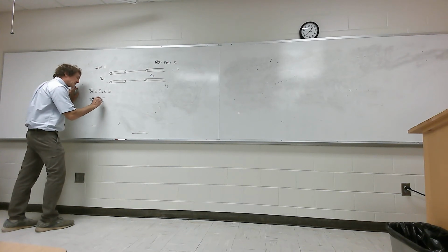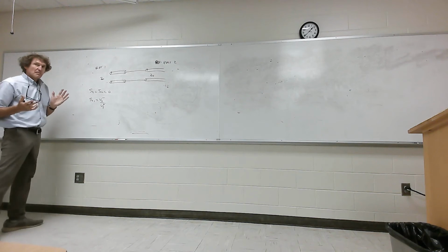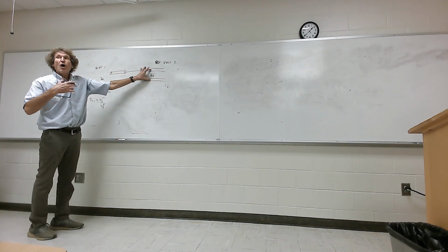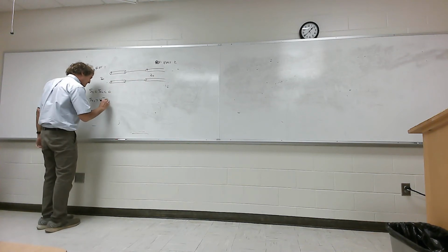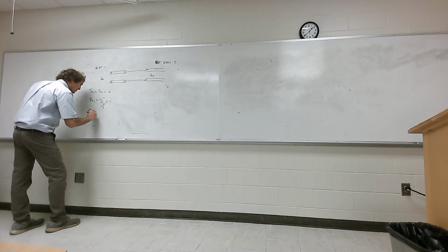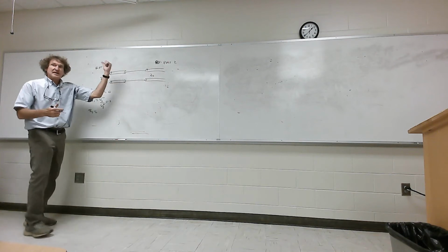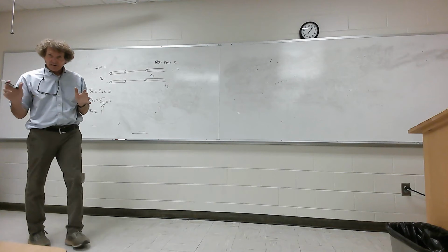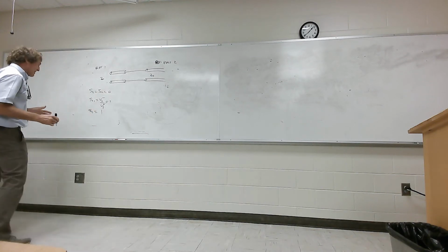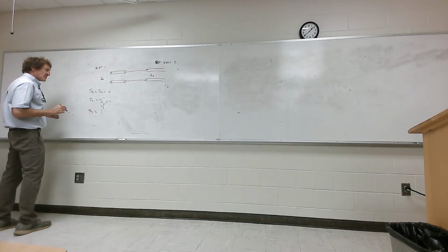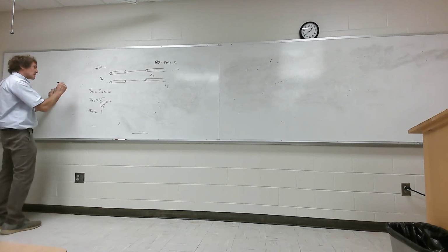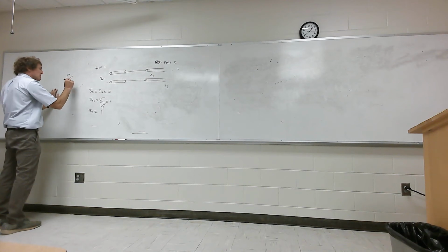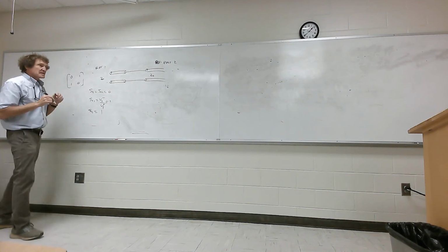Now, what is S21? That's V2 minus over V1 plus by inspection. How much of this signal gets over here? All of it, so 1. What is S12, which is really coming from this way? How much of that signal gets over there? Class? 1. That's a no-brainer, all right? So you've got zeros on the diagonal, 1s at the corners, right? It would look like this. For this one, it's 0, 0, 1, 1. That would be the S parameters for this one.